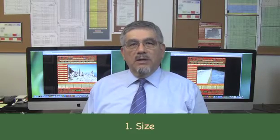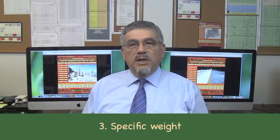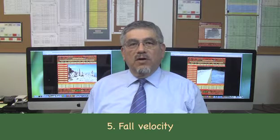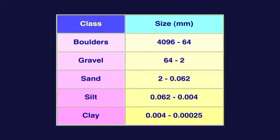The particle characteristics are 1. Size, 2. Shape, 3. Specific weight, 4. Specific gravity, and 5. Fall velocity. A classification of sediments according to size is shown in this table. 5 groups are included. 1. Boulders and cobbles, 2. Gravel, 3. Sand, 4. Silt, and 5. Clay.